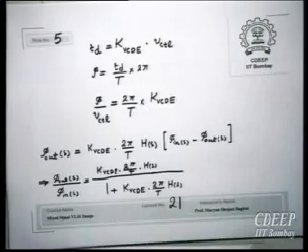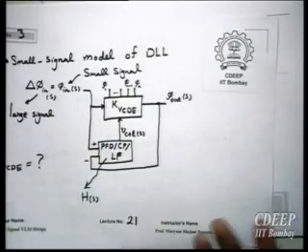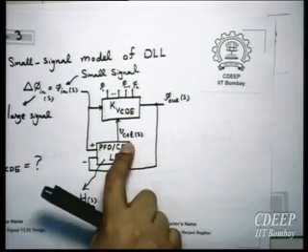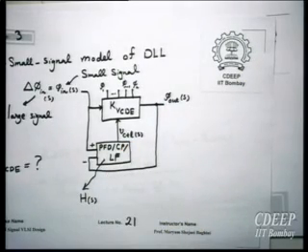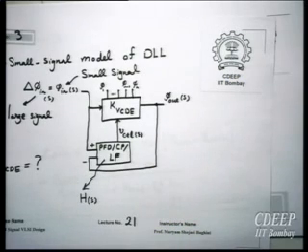However, it doesn't change anything, because here you have a fixed phase, fixed frequency, which is given to this delay element. What we are interested in is how much phase shift it generates because of VCTL. When we are talking about phase shift, what matters is phi in? Because this phi out actually is not phi out, it's actually phi out minus phi in, the amount of phase shift.